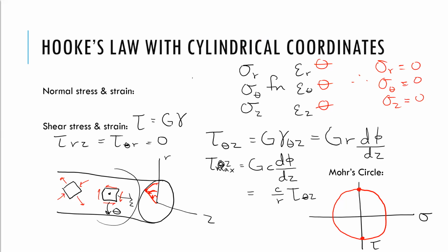All right, you just want to go the same way as the shear stress? It's like the right hand rule, because R times theta has to equal Z, right? X, Y, Z, R, theta, Z. So if you had your X coming towards you and your Z going towards the right, your Y would have to be going down. It's the same thing with cylindrical coordinates. But because things are circular, it's really easy to get yourself turned around and think that theta is going the wrong way.